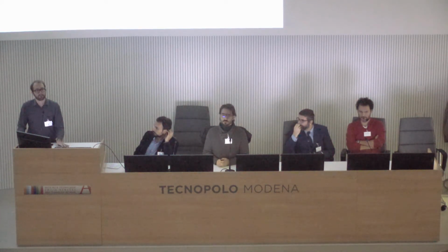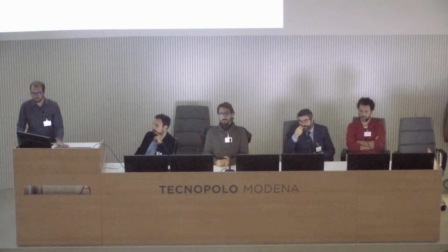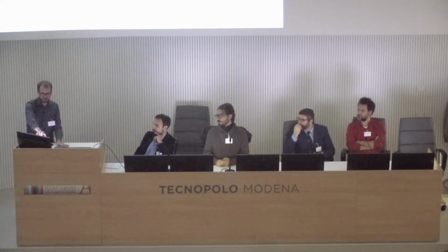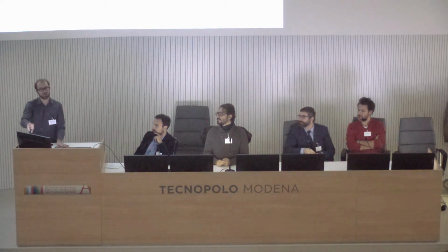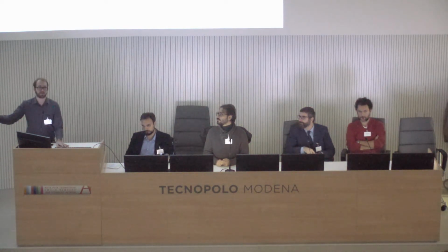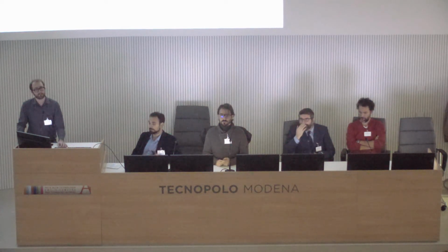And then you use the stress intensity factor as a failure criterion. Yeah, these SIFs were computed using a plastic behavior, and of course the Paris law is elastic because it doesn't work in plastic conditions. So the crack propagates according to the stress intensity factor. Exactly.